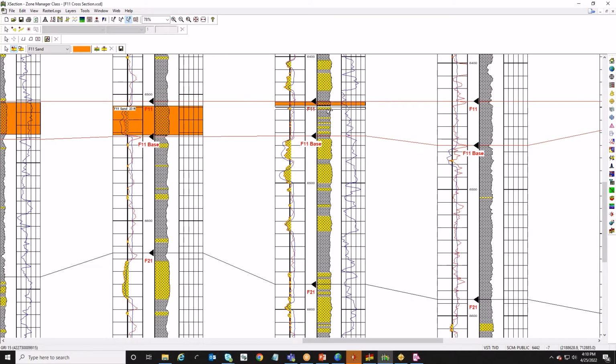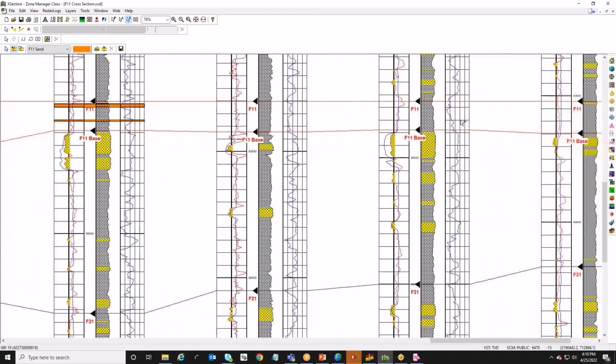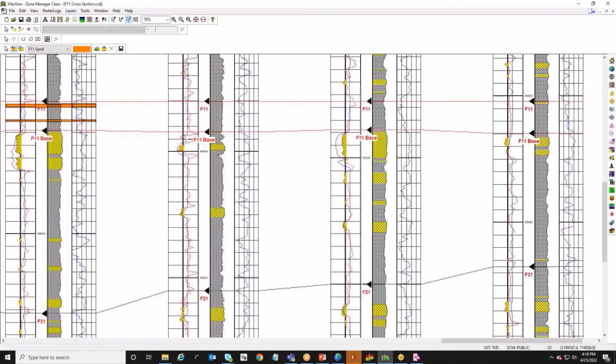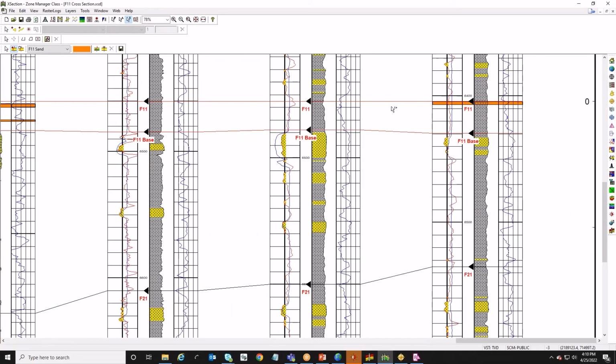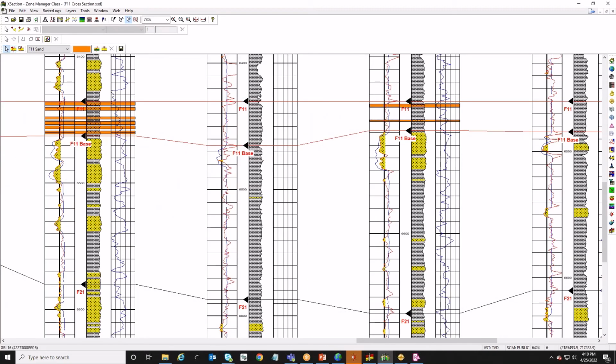But what I do want to do is indicate in that well that there is in fact no sand within it. Because when I save this data and I come back and some of them come back null, I might think that I accidentally missed the well. When I come back and look at it, I want to realize I did not miss the well, it is in fact that there's just no sand within there. So let me go ahead and pick all the ones that have a sand first. Yep. And then I'll come back over here to this well.